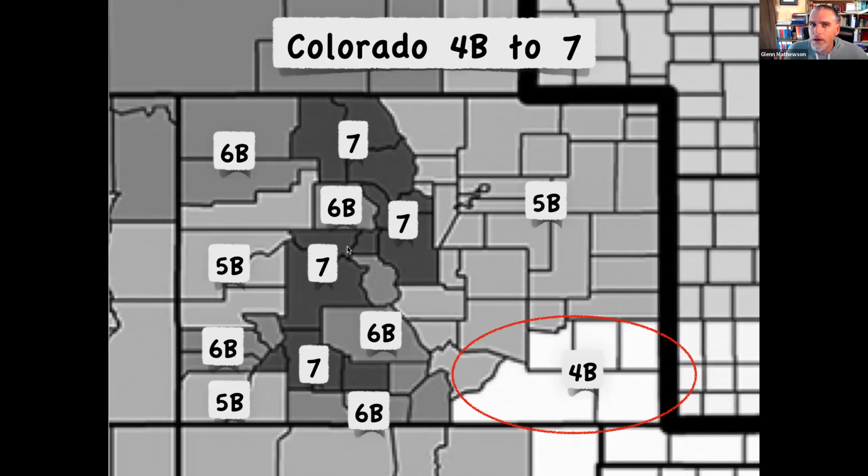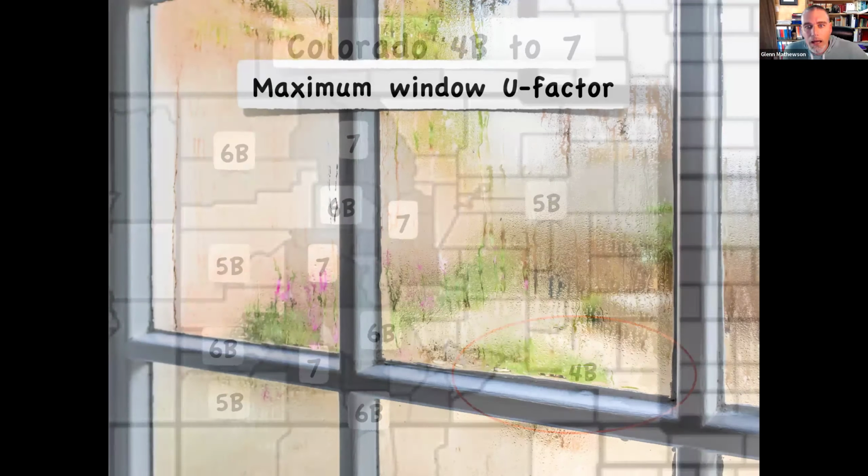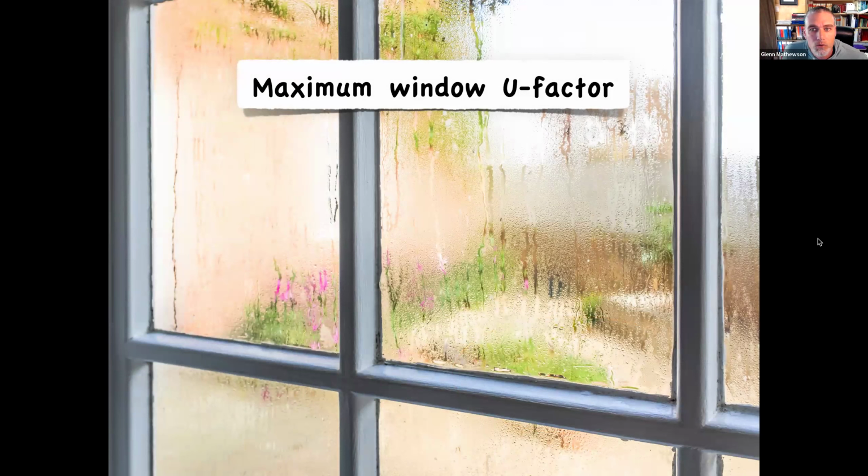Well, remember what I said? Thermal performance is directly related to vapor management. So if you start putting in crummy windows that allow heat to move right through, no problem, because you've offset it with something else, you're going to have condensation forming on the inside of those windows, like the old single pane windows. Who's got an old house? I've replaced my windows. So we see some thoughtfulness: yes, we're talking about thermal energy and energy conservation, but we still have a duty to protect from condensation and moisture and vapor issues.